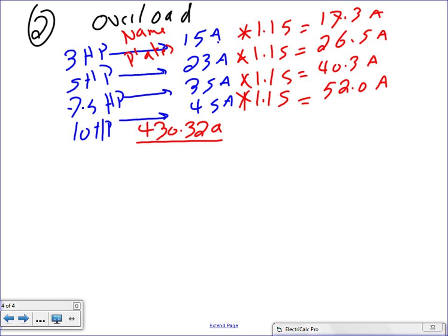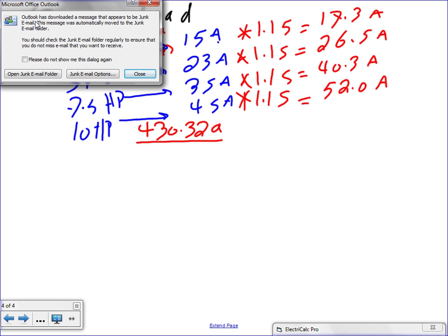What do you do with the overloads? Leave them alone. So you're going to come up to the overload. Can you guys see this overload here? Reset overload. I have my overload right here. I don't know if you see that little screw. You grab your screwdriver. These little dials here are my overload. You can come here and adjust them. You have to adjust them as close to 17.3 as possible.